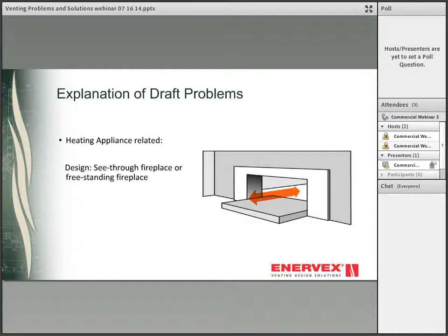Among critical fireplaces is the see-through fireplace, a fireplace that is open to 2 rooms. These types of fireplaces must capture the air in the same way as an exhaust hood, which requires good draft in order to maintain a high velocity over the fireplace opening. Very often, turbulence can be experienced inside the smoke chamber, and smoke problems can occur. This problem can occur when a fireplace was converted from a one-sided fireplace into a see-through. This can also occur when a smoke chamber is non-existent.